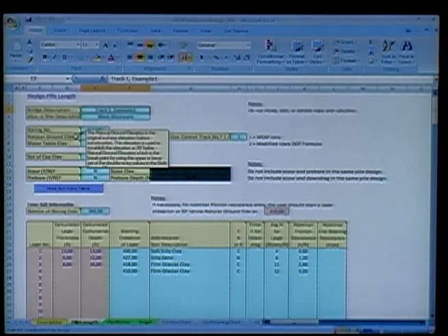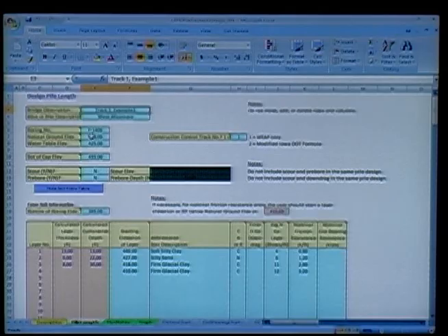Natural ground, the only thing I'm really using that for is, where if you're in a glacial clay, if you're 30 feet below natural ground, you get to use a higher or lower value depending if you're above or below. So I use that, subtract 30 feet, and it kind of tells you maybe I should put a layer at 410 because I get to use a better value below that.